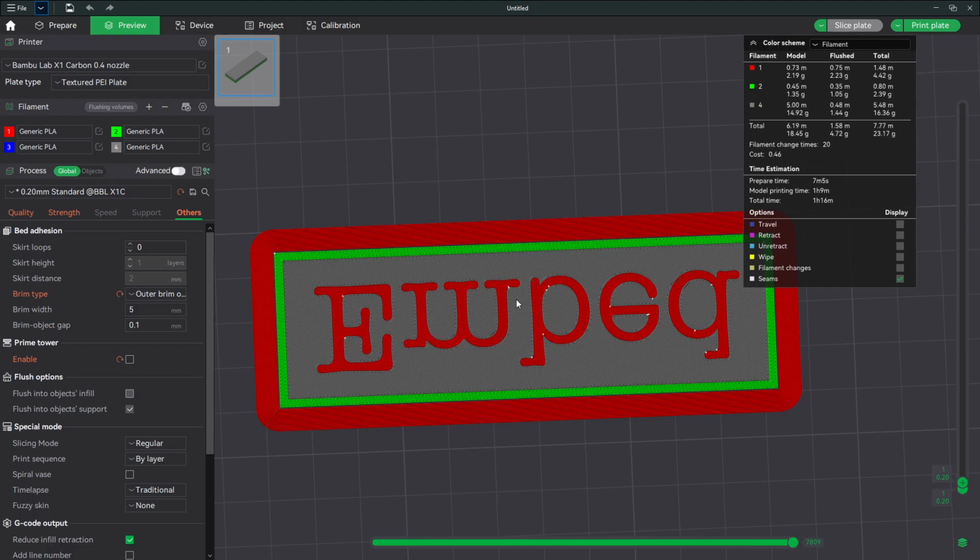I wanted it to do that because I was only printing a very, very thin part, only 3 layers thick. By doing the 2 black layers and then switching back to white, it would do all of my white with only 1 switch to black before going back to printing more white, which meant if there were any little wispies or hairs that would have been dragged from the black printing, I had about 1 minute and 5 seconds while it did the color change to white to pull those off the plate, brush them aside, make sure that I didn't have any of those little hairs in the way that would have gotten embedded in the next white, which would have shown up because it was a light box.